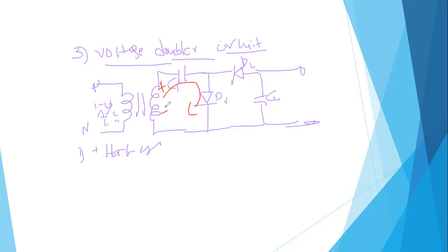During the negative half cycle, this is negative and this is positive. So D2 will be forward biased. There C2 charges up to V maximum. Here C1 already exists, that is V max, and coming from the supply, we can get the value that is 2 into V maximum.